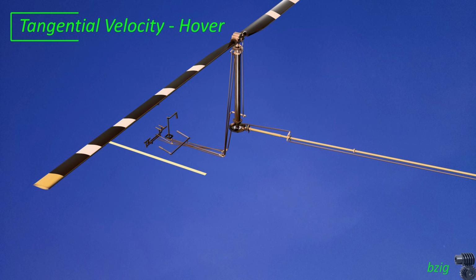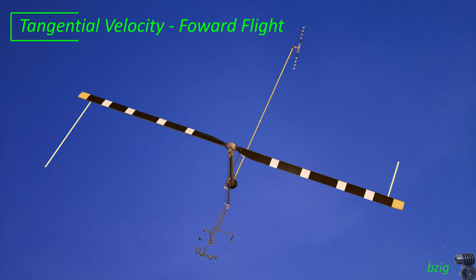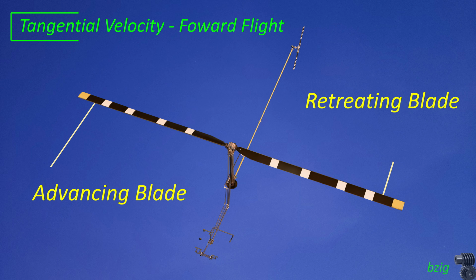Here I'm sliding the vector along the span of the blade so you can see the change to the tangential velocity based on radial position. And by the way, my math assumes the rotors are always rotating at 100% RPM, so you see this effect in my 3D model here whether or not the blades are rotating. Now I've changed the forward flight speed to 130 knots. This is so you can visualize how tangential velocity changes due to the blade advancing into and retreating from the relative wind while in forward flight.